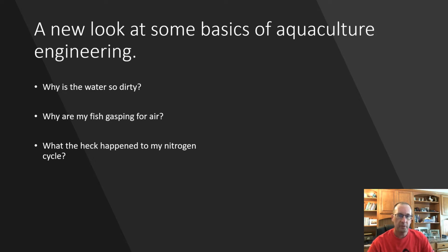The other thing that you need to recall is that the RAS components are not only there to hold the fish, but to remove the solids and any nitrogenous waste, which is what we call the mechanical and the biological filter respectively. They're also there to help circulate water, maintain temperature, and provide oxygen and take out any carbon dioxide. So everything has to work together.